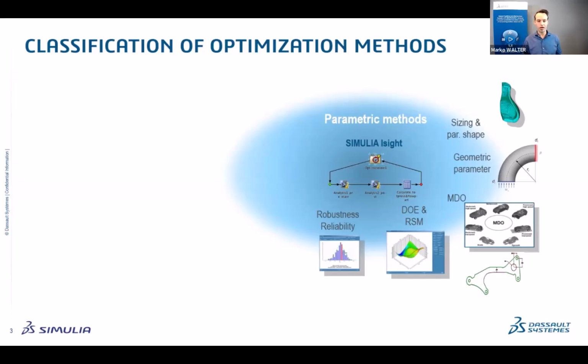In this case, I'm referring to iSight, which is basically the standalone product, where on the platform you have the applications, process composer and result analytics based on this functionality, which is doing things like response surface method calculations, design of experiments. You're able to do Monte Carlo analysis, uncertainty analysis, all these different things to automate the process of simulation and optimization. But it's all parametrically focused.